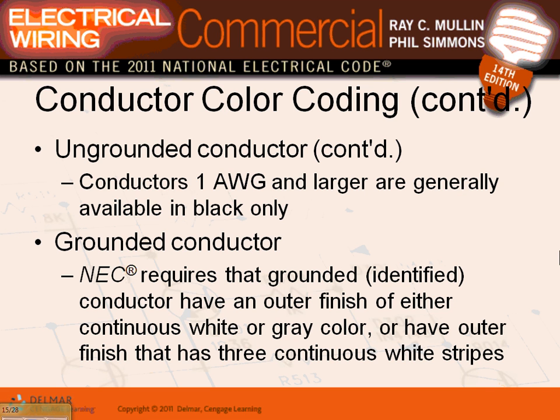And the code says right to left A, B, C, front to back A, B, C, top to bottom A, B, C. And if it's other than this because of old equipment, you have to identify it by writing next to it.